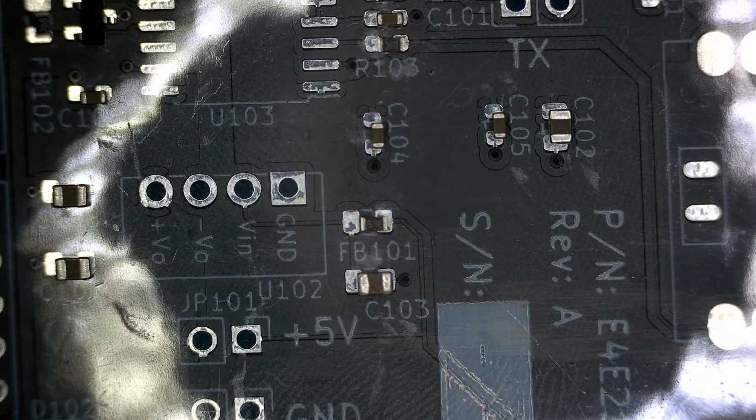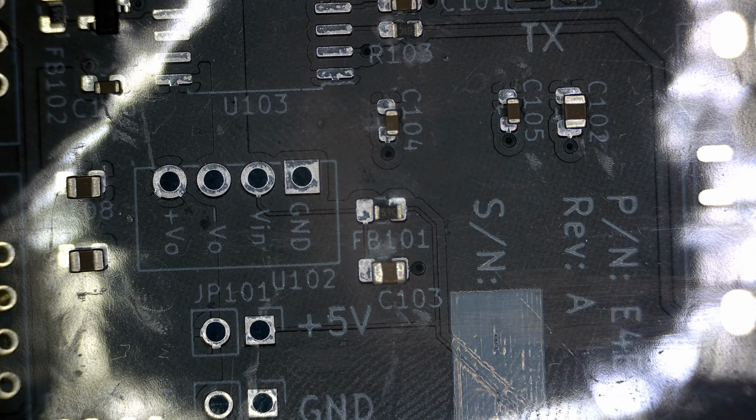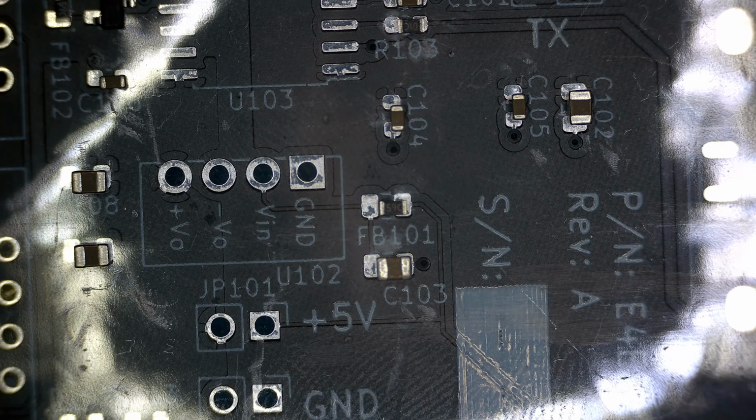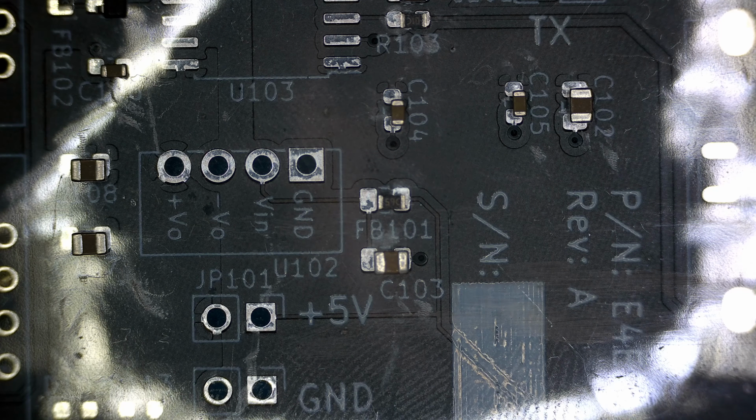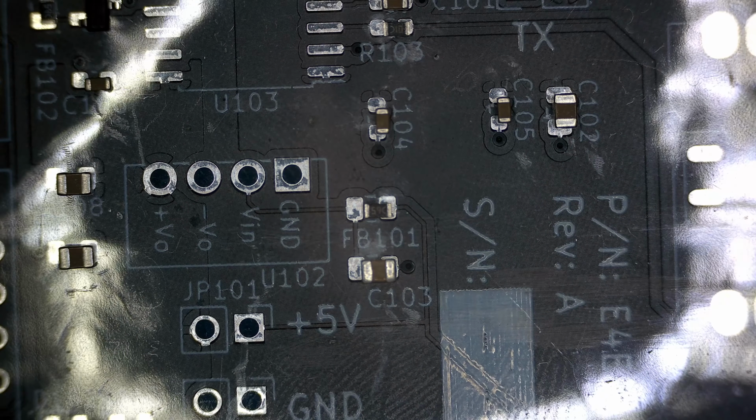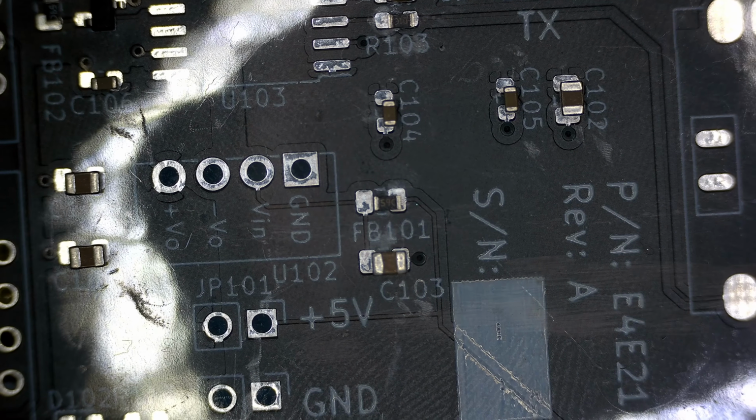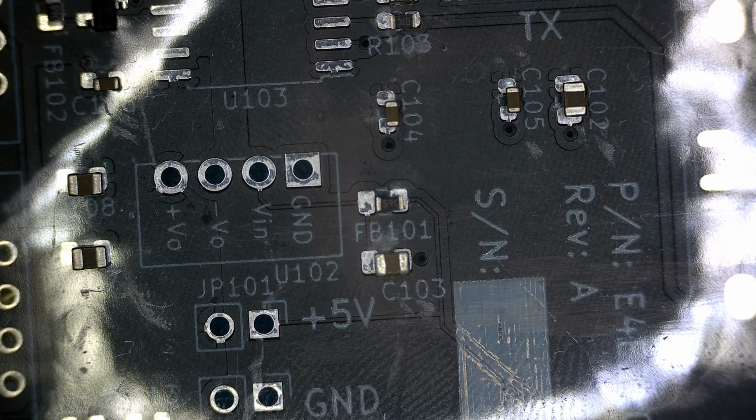For example, if the nozzle to camera offset is not correct, you're going to see an offset on every single component that gets placed, because it's homing every single component based on where that camera is. So that offset needs to be dead on.